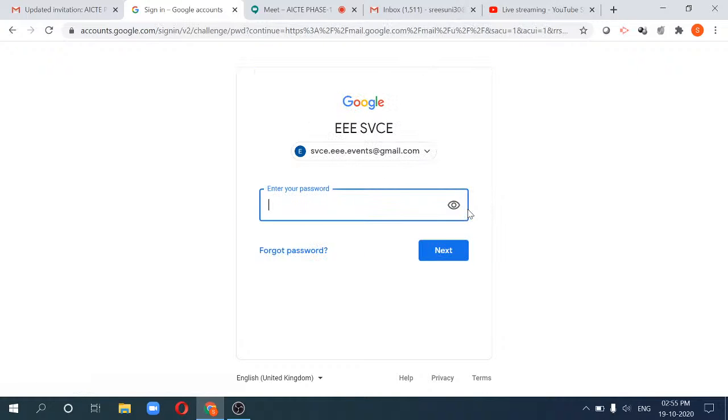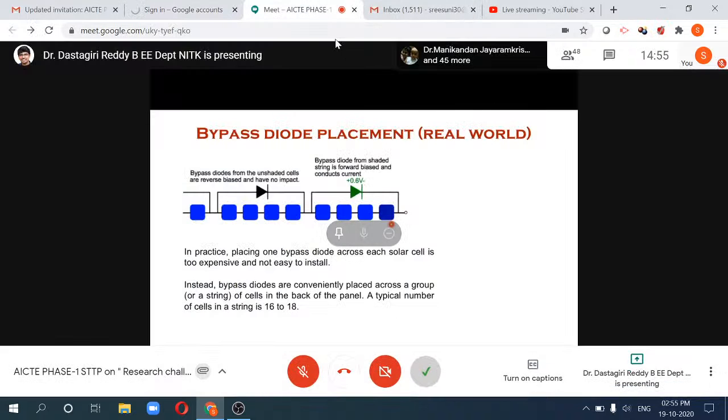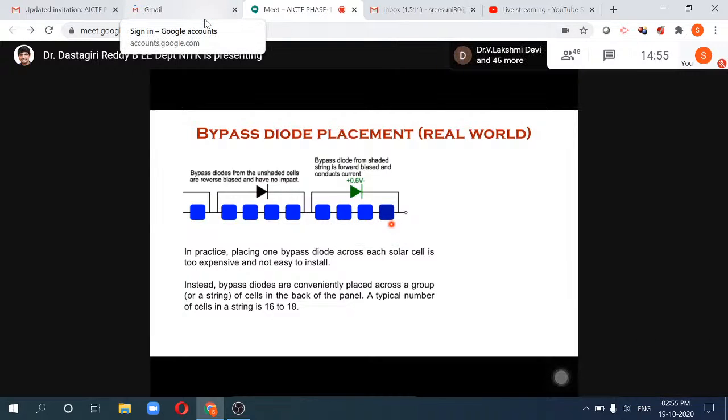But there is some research in connection. Instead of connecting all in series, if you connect in a different way, with a position of cells in different locations and connecting them using some logic, then there are some research papers showing that you don't have to rely on bypass diodes, but you can get rid of the effect of partial shading condition. There are a lot of papers available on partial shading conditions, and you can also explore those things.